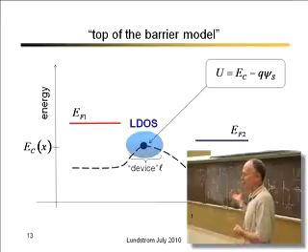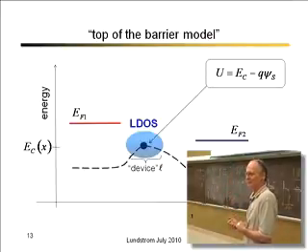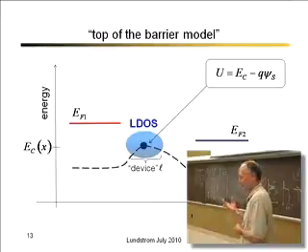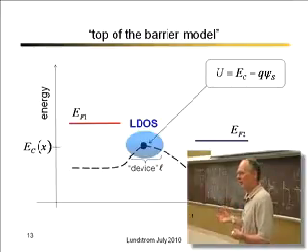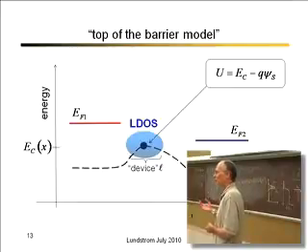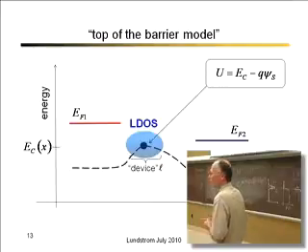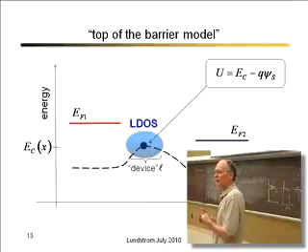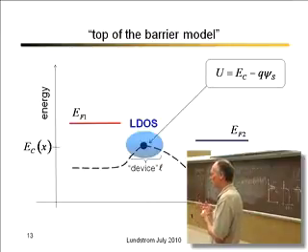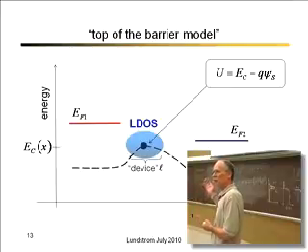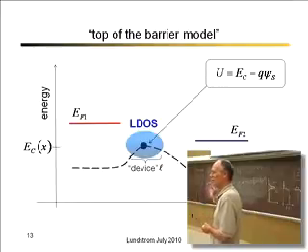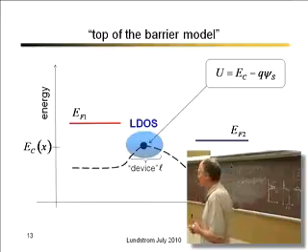So at the top of that barrier, we have some density of states. The easiest way to think of it is, if it's a silicon transistor, I'll just think of that as some silicon band structure, and we're going to move those states up and down. Now you might wonder, if you get into a really small device, you may not be able to use a bulk band structure. The local density of states there might be modified. Then you need one of those quantum simulations that we discussed earlier. But this really works very, very well, even down to dimensions that are well below 10 nanometers in practice.